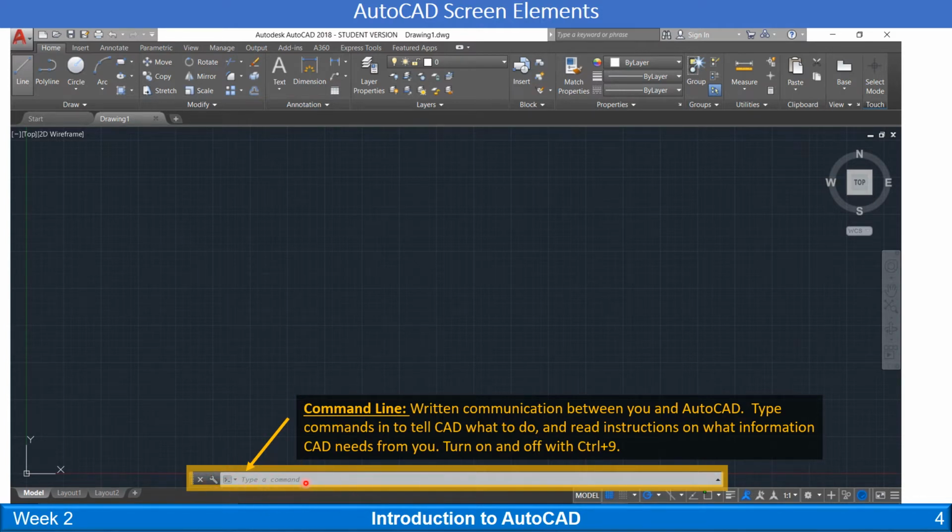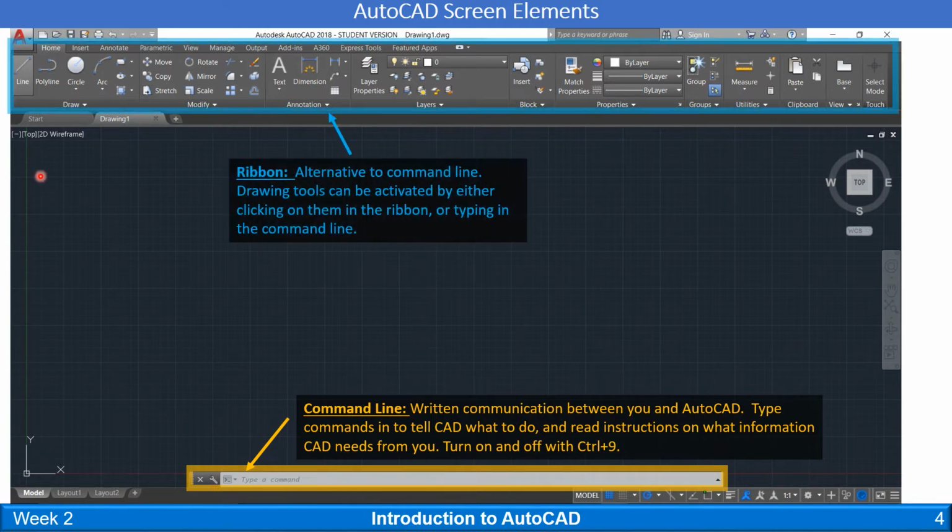So if AutoCAD needs information from you, it's going to ask you questions, and you're going to answer in here by just typing in this little command line. The other way to input commands is the new feature, and this is how a lot of the other CAD software works now: they put all the tools up here in what's called the ribbon. So you can see there's drawing tools with lines, polylines, circles. Each one of these little shapes has a pull down menu with multiple ways that you can define that circle, or multiple ways to define an arc. So just explore some of these tools in here.